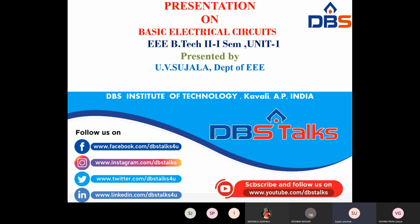So when there is a voltage source, minus to plus, plus V1. Plus to minus drop, that is minus. What is the current flowing? I into R1, so minus I into R1. Then I into R2, plus to minus, minus. Plus to minus, minus V2. Plus to minus, minus I into R3. Next, plus to minus, minus I into R4. Next, minus to plus, plus V3. Next, plus to minus, minus I into R5. Minus to plus, plus V2 is equal to 0. That means the algebraic sum of the voltages is equal to 0, which is nothing but Kirchhoff's voltage law.